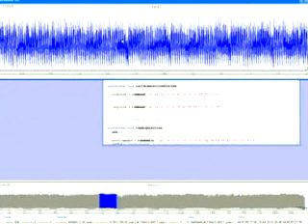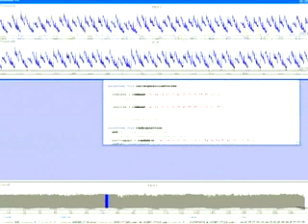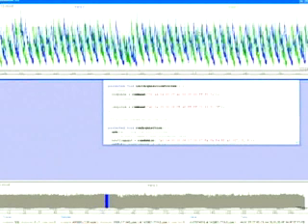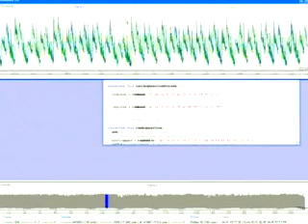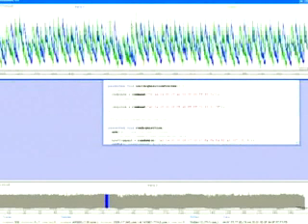If I zoom in a little bit on this trace, you can start seeing the clock cycles happening. Now this is a typical image of what we see. Like all the peaks that Job showed before in the slide is all the transistor switching, which goes down, and for each clock cycle you have a peak again. But if I overlap that with a second measurement, you'll see that there's misalignment. I can show you that visually by just grabbing one of the traces and aligning them manually. Like this is what we want to have, and this is what we have right now. Now, of course, we're not going to align them all manually. We have some more advanced stuff for that.